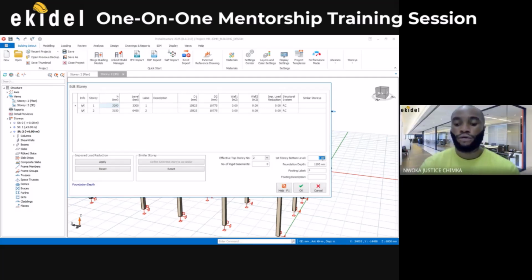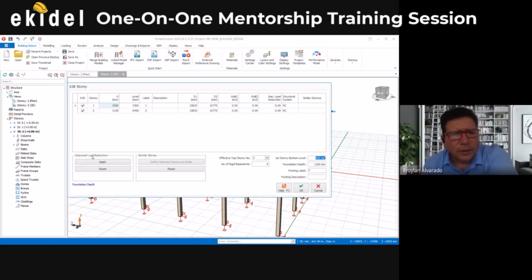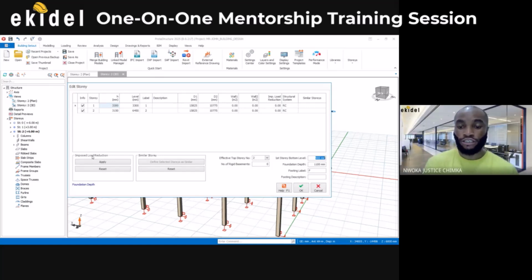Oh, okay, that's fine. So then come in and put the value here, 900 here. So you put it under the first, this place here. Okay, all right. You put it here, and then that's all. Later, when we're doing high-rise buildings, I'll show you how to apply this here that says impose load reduction. Exactly, but not for this building. This is very, very small in height to do that.